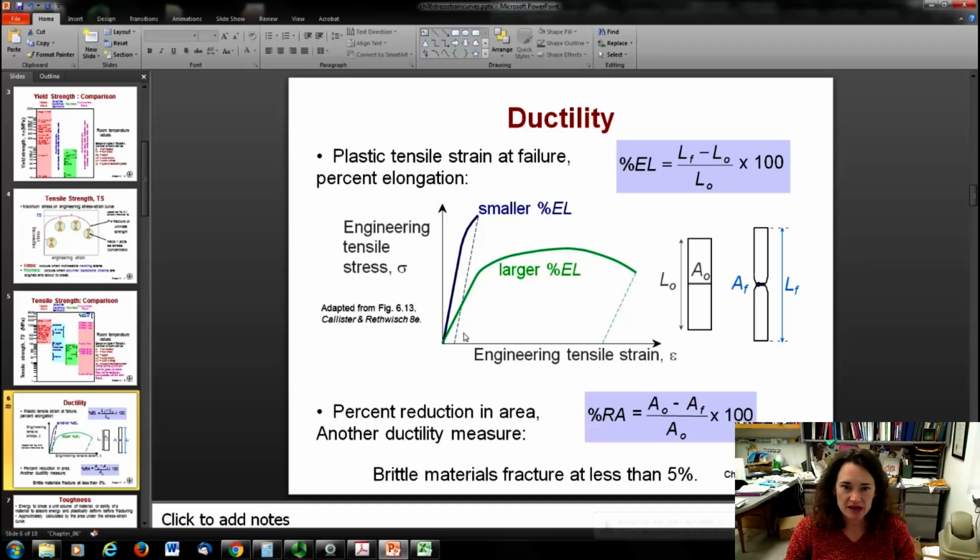You can see here that they're sort of backing it out and doing the fit and extrapolating, but remember that yield strength, they're comparing the yield value here to get the plastic, but oftentimes that yield is not a very high number. It's like 0.002, and so you can usually ignore that for the test that we'll do in class.